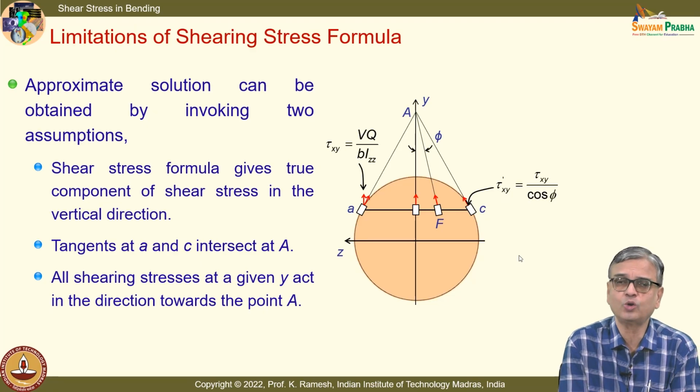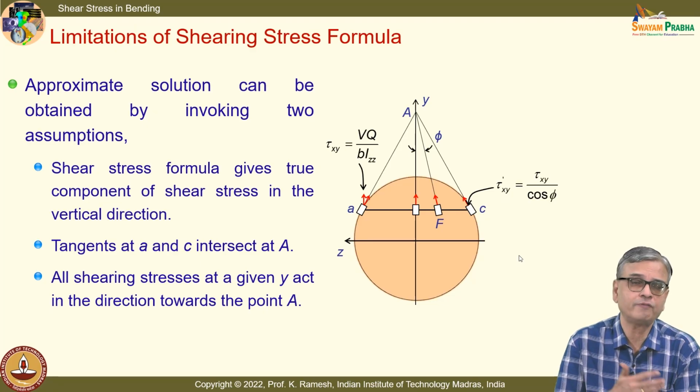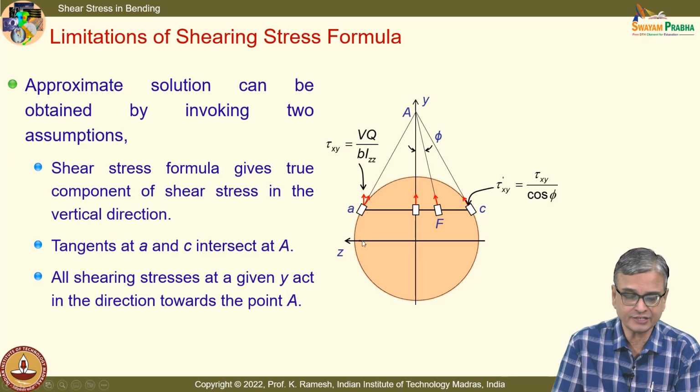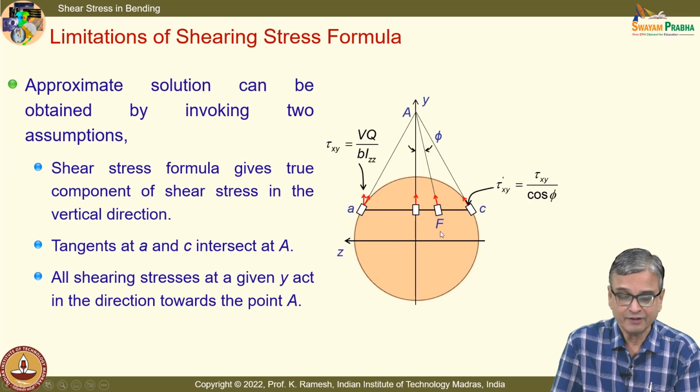See, the way you have to look at it is, if we want to find out the shear stress importance in bending, it reaches maximum at the neutral surface. For the circular shaft at the neutral surface, the result is very close to what is predicted by theory of elasticity. The distribution is just to satisfy ourselves how the force is distributed. For all our practical calculations, we will actually find out only at the neutral surface, or the neutral axis, whichever way you do it.